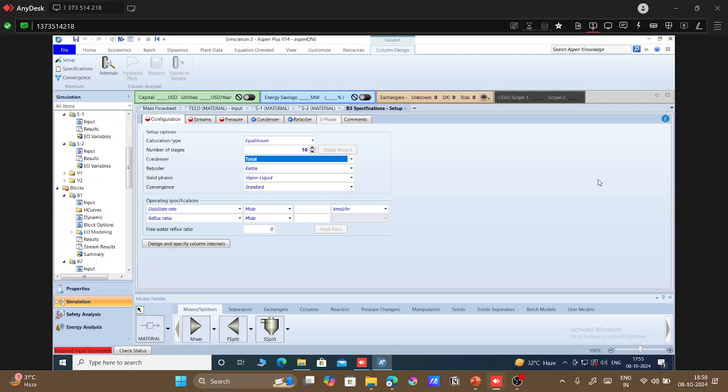So here we have vapor liquid equilibrium, but the third phase, which has a larger amount of water, can be treated as a separate phase, so it doesn't have any equilibrium with phase 1. As you can see, we have a mixture of acetone and EIPK, out of which EIPK and water do not have any negative Gibbs free energy values, right? So their mixing is not possible.